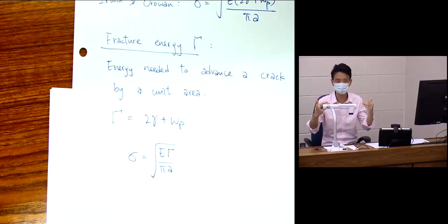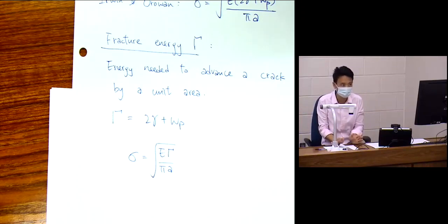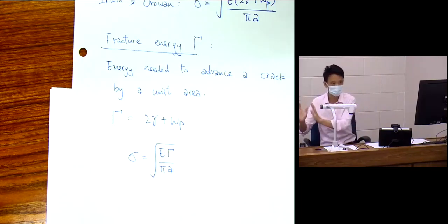It is the same as the classical strength theory you learn in solid mechanics. You put that amount of stress, and it has some critical failure stress in the material, and if the applied stress is larger, then you break it. If not, then you don't break it, right? So same here, but now everything changes to energy. It's not stress. Everything changes to energy, but the idea is the same. We apply some energy, and there's also a fracture energy in the material.